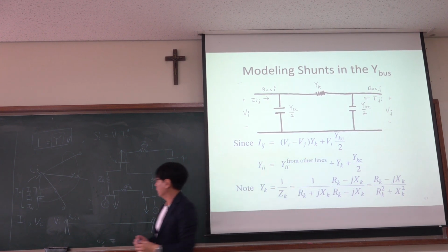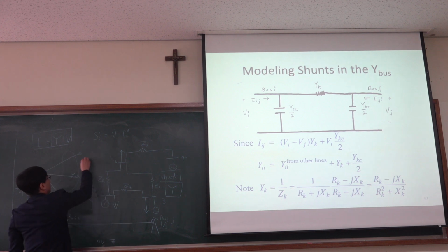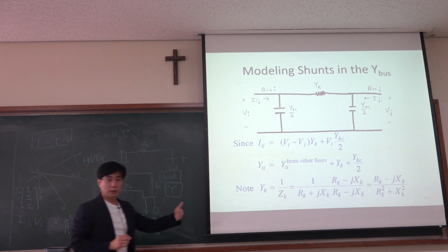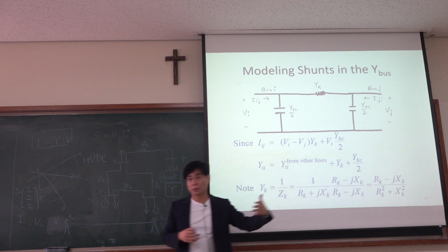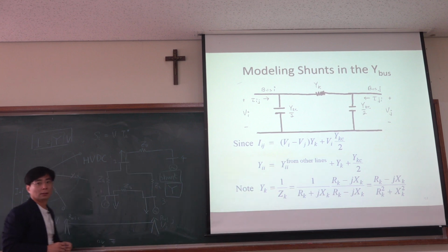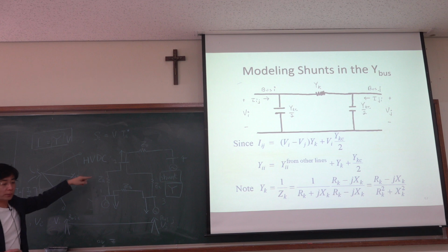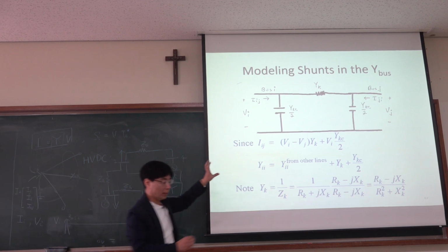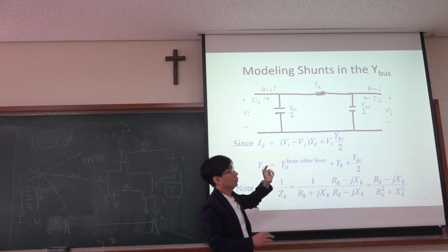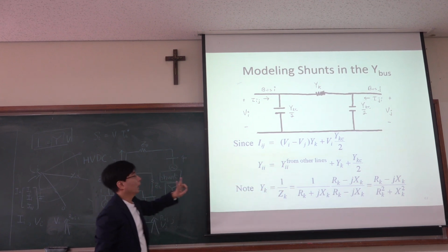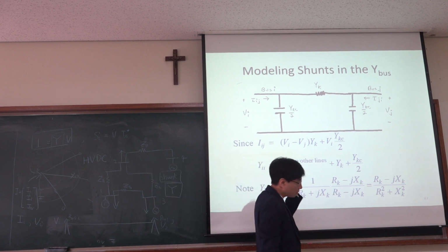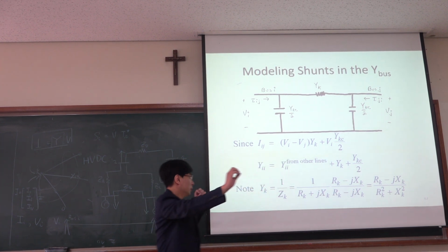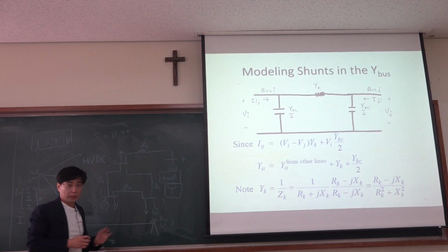That's why we use high voltage DC lines for long distance transmission. If the distance is more than a few hundred kilometers, then we need to use DC transmission, high voltage DC. The mainland of Korea and Jeju Island are connected by 2 HVDC lines. And in a bigger country like China or the United States, long distance transmission is based on HVDC.